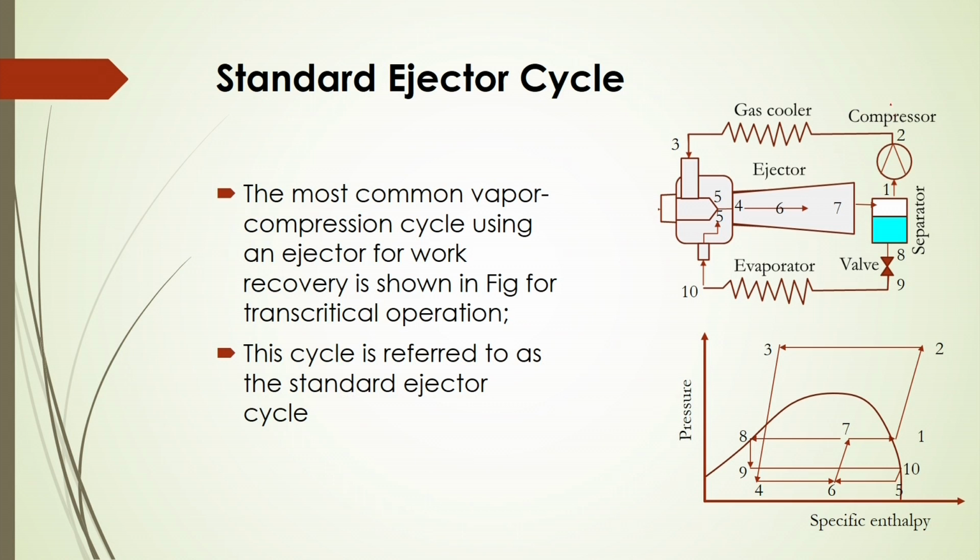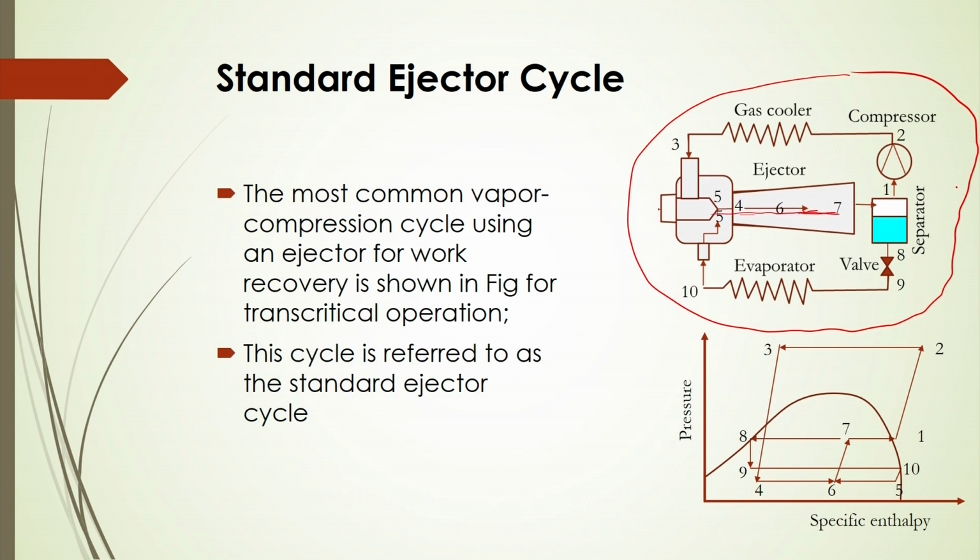So, here in the figure it is shown that this is the ejector system, and through this ejector system the gas is coming through the ejector as a jet, and then it will be separated in the separator, and then by the compressor the gas will be supplied here. And here again from this separator, liquid will be passing through the evaporator section for controlling the temperature, and it passes through this ejector system, and this way continuous cycles will be applied there,